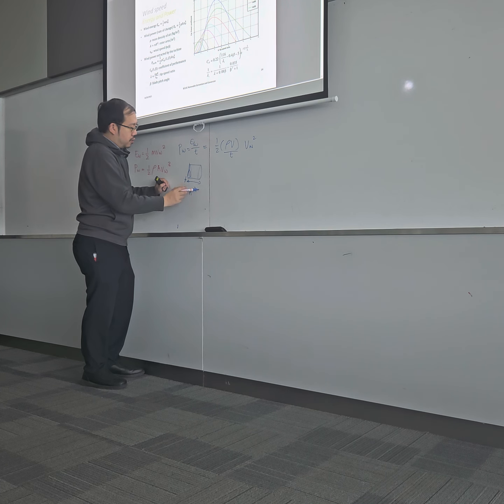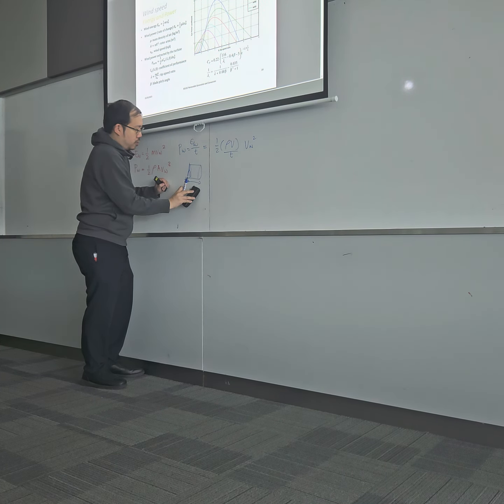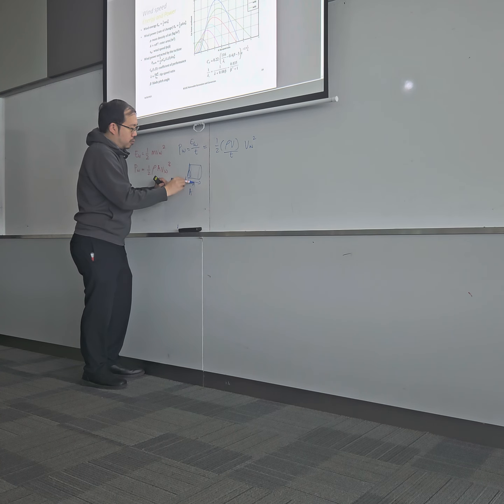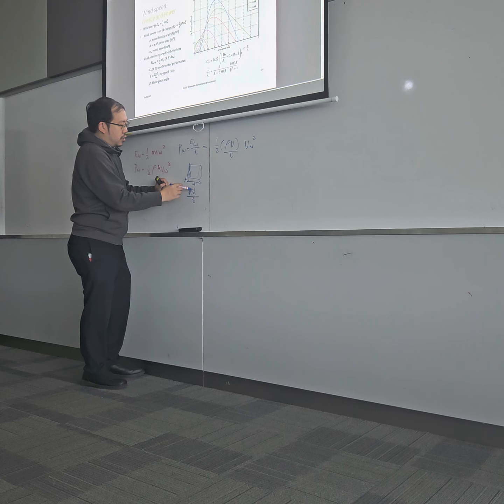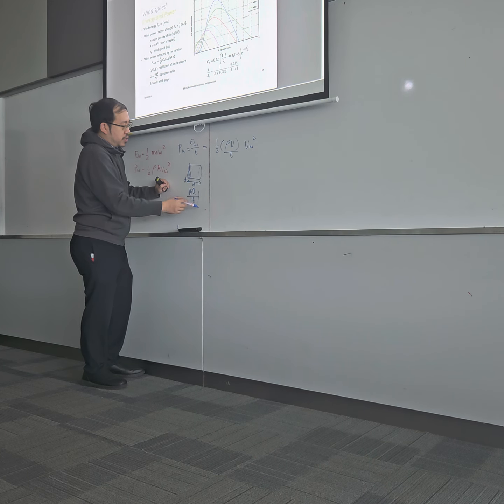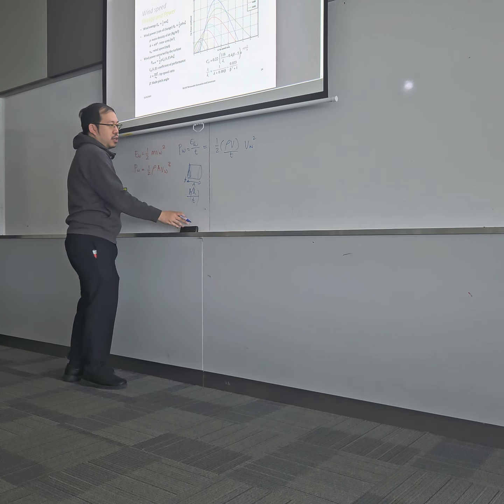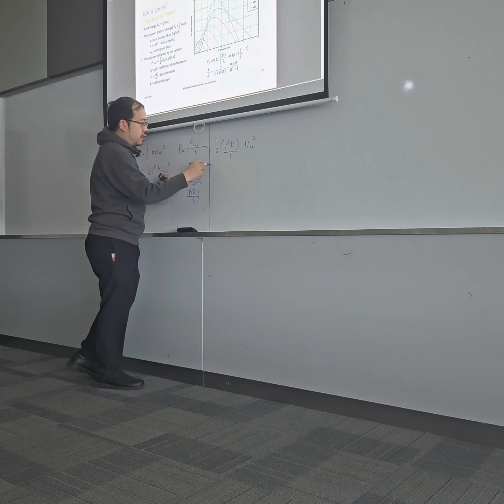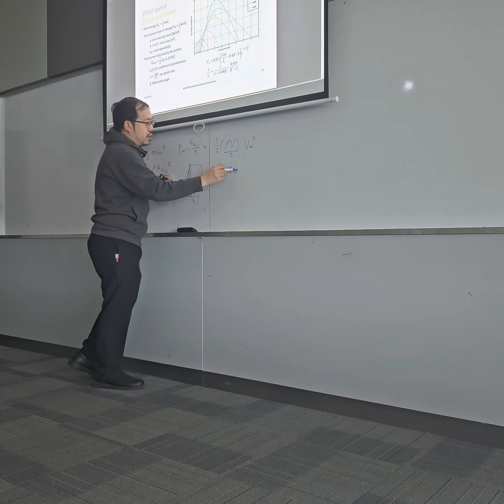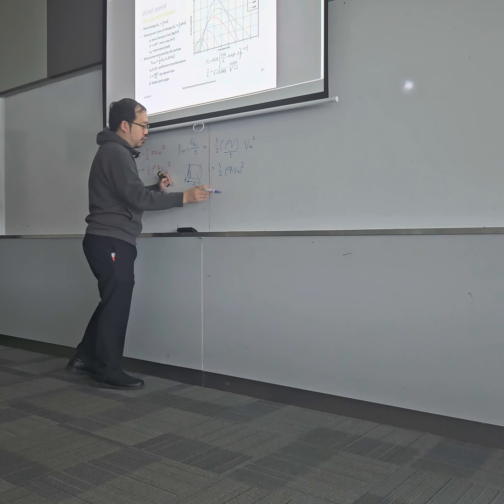So this is equal to meter per second. So you can just equate it to the wind speed. So lastly you get half rho A wind speed cube.